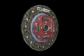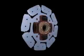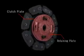Next, looking at the clutch disc assembly, engine torque is first transmitted from the pressure plate to the facing material. This facing material is supported by the cushioning plate, which makes half-engaged clutch control possible. Engine torque is transmitted to the retaining plate and clutch plate, which hold the entire assembly together while actuating the torsion springs.